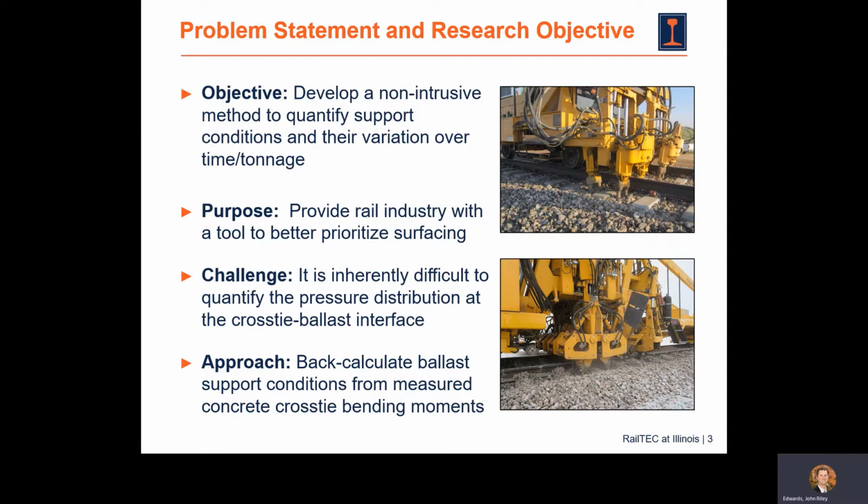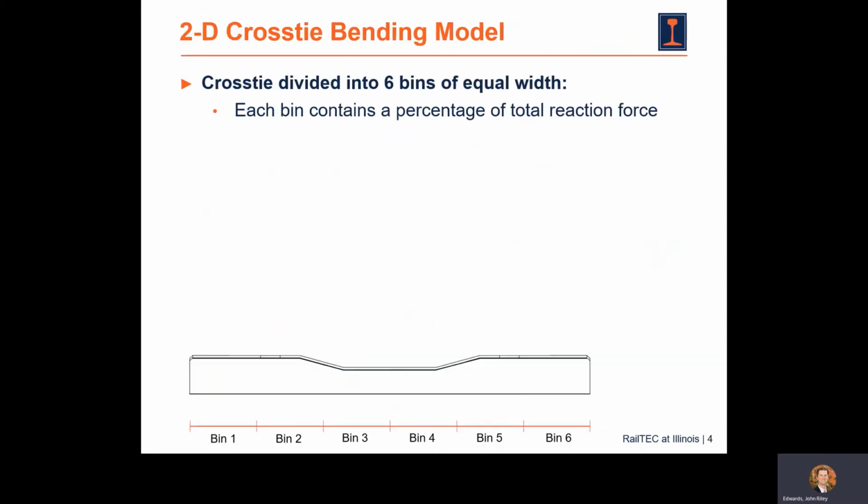So our approach was to back calculate the ballast support condition based on measured bending moments collected on the crossties. And much of the data I'll present were actually captured while conducting research aimed at optimization of concrete crosstie designs.